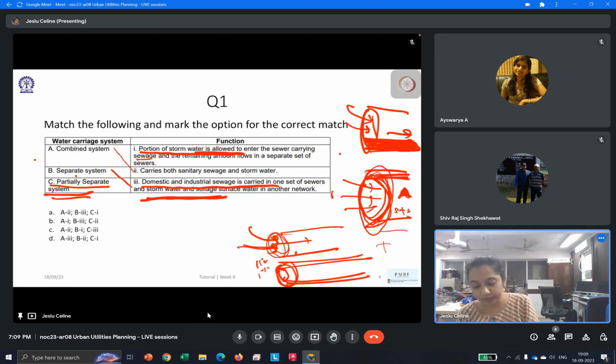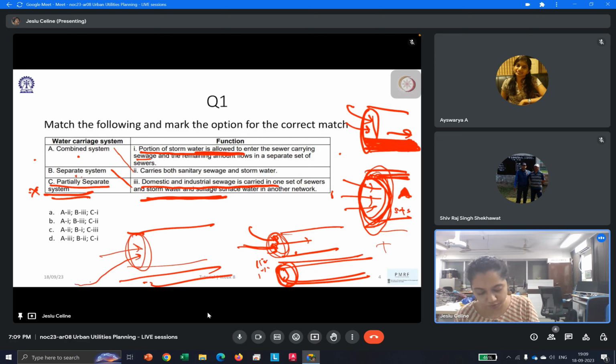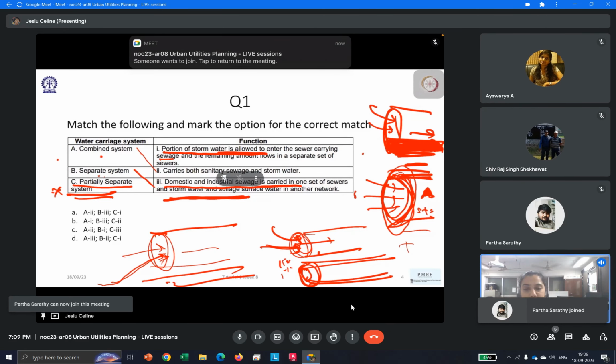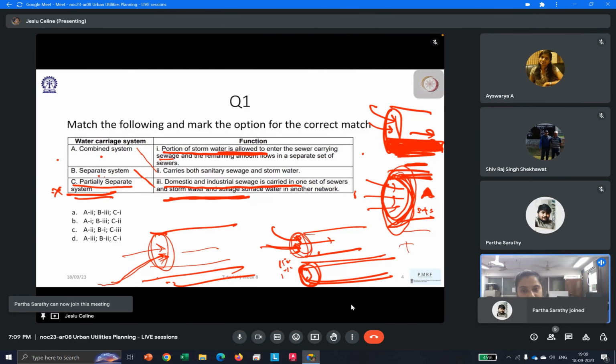This can be said to be a combination of both, where you have the sewage system and also a separate stormwater line. You can channelize a portion of your stormwater to go through the sewer to get the self-cleansing velocity, and to avoid blockages or accumulation of sewage inside the drainage pipe. At the same time, you will not be overburdening the pipe.